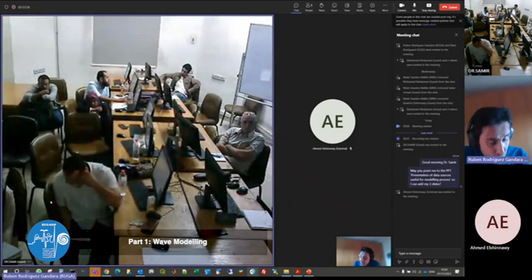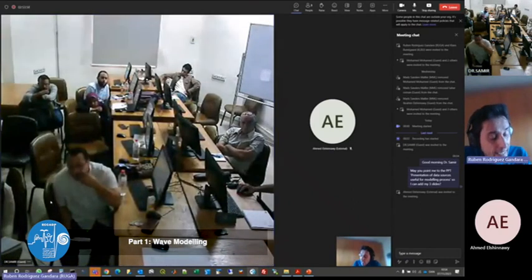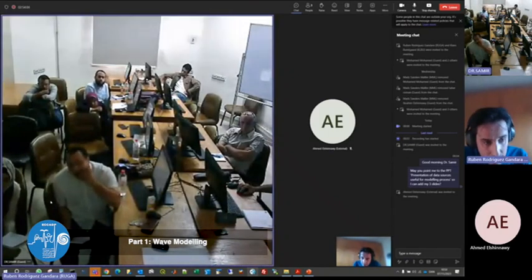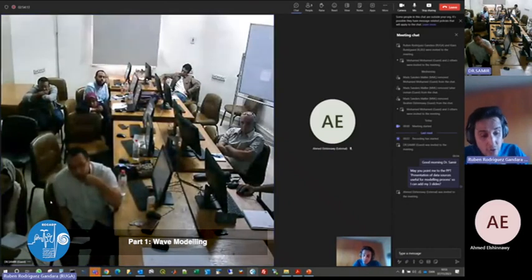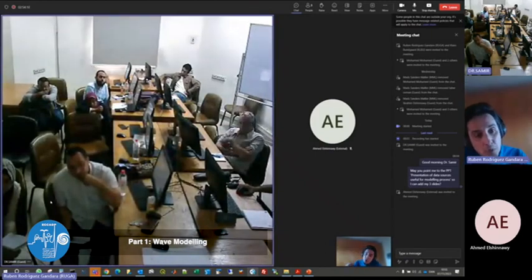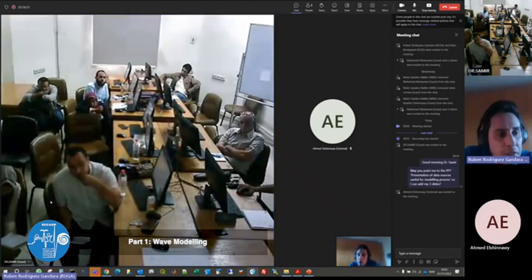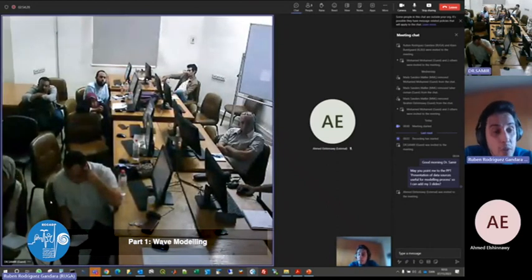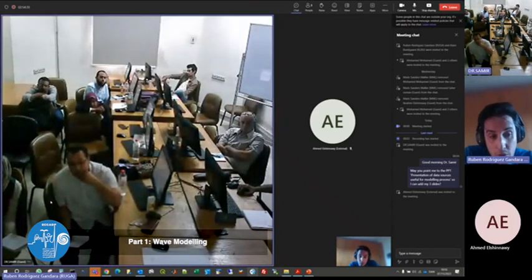And nearshore, in case you can afford the computational time that adding the triads is going to cost, then switch on the triads. Especially if you are going to investigate the nearshore shallow water current patterns, you need to have the triads because the triads contribute to the current pattern. But only if you are interested in very, very shallow water, I don't know, 1 meter, half a meter, something like that. And for that, you will need a very high resolution mesh, and you will need to make sure that you have a well-defined bathymetry. That's up to your judgment.